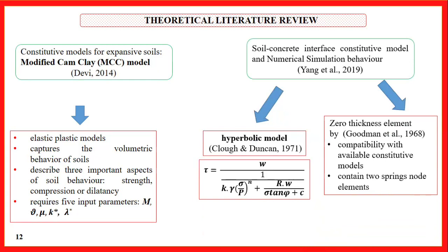Soil-concrete interfaces also have many constitutive models, such as the hyperbolic model developed in 1961. Also, the zero-thickness element is a model compatible with available constitutive models and contains 2 spring node elements.